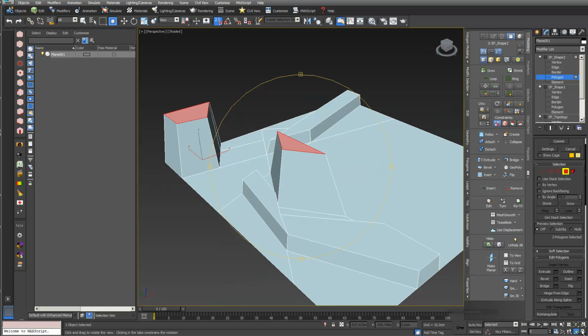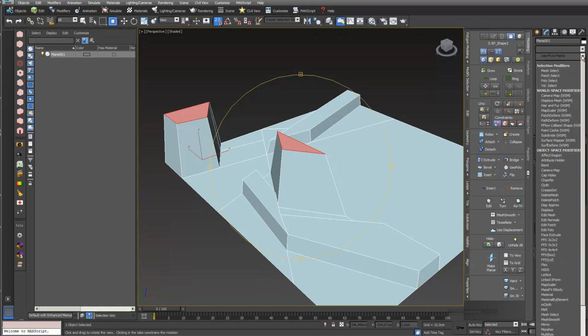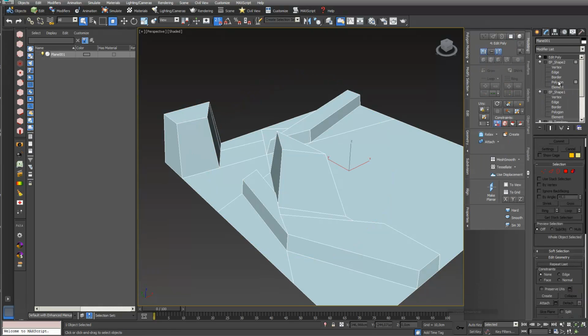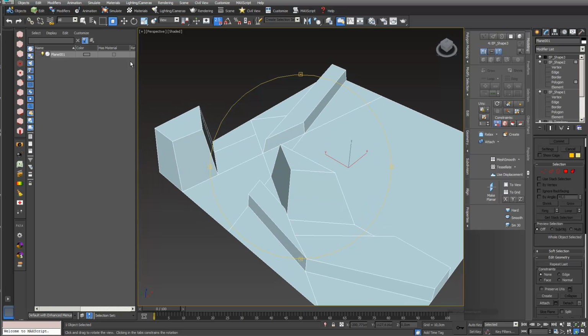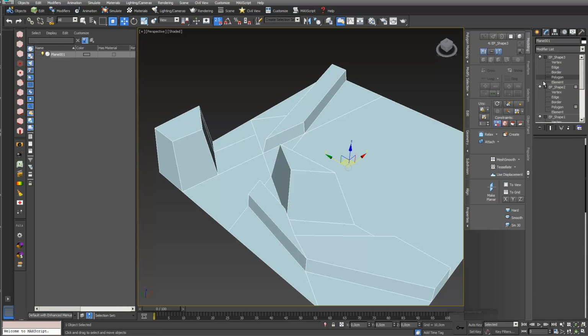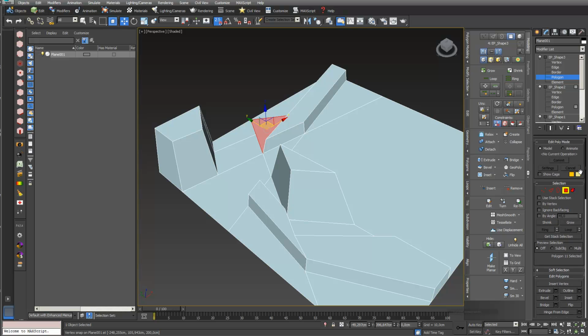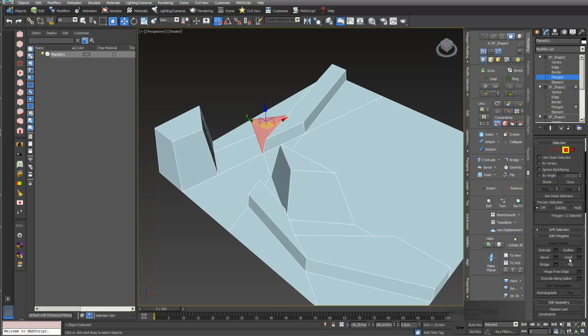For the landscape, there are probably very few other interesting functions, so I just go and say edit poly, right mouse click, EP, shape 3. So I just choose another surface. Let's see, I just choose this one, and I go into my edit poly and I select this, and I use again my animate mode, and here there's something like hinge from edge. That's already quite complex.